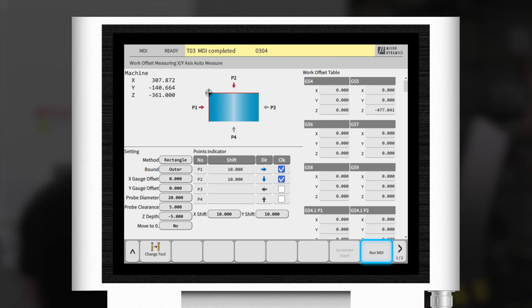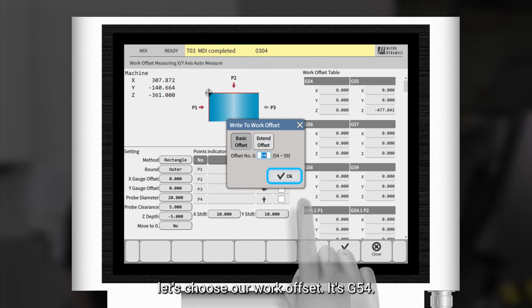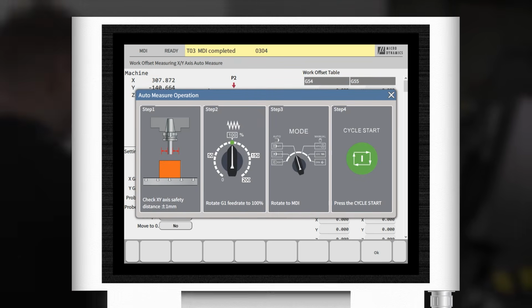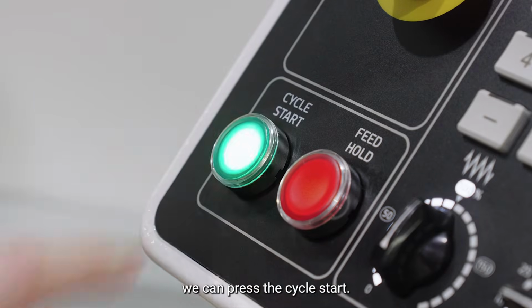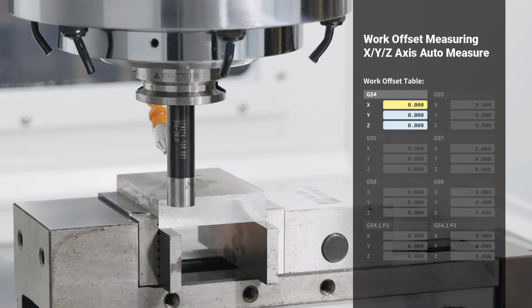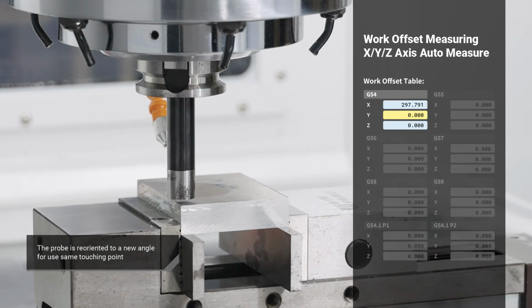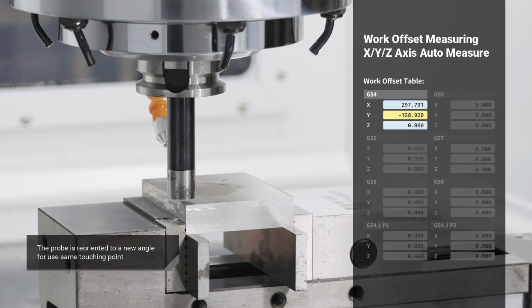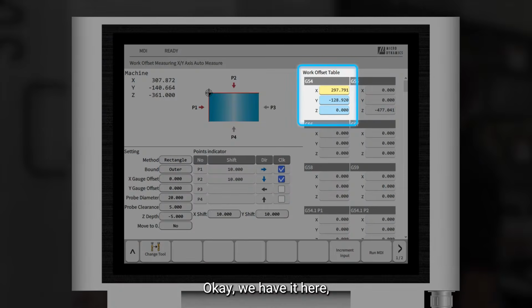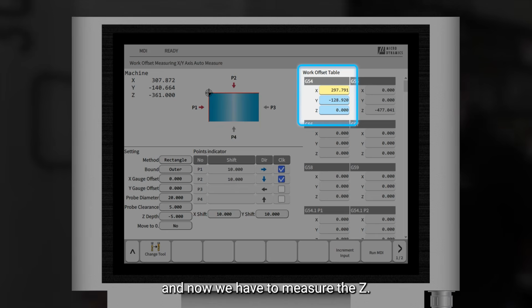The machine is going to do it automatically. Let's see. Run to MDI. Let's choose our work offset. It's 54. Let's check everything is okay. Let's put the machine into MDI mode. We can press the cycle start. Okay, we have it here. We have the X and Y G54 on the work offset table. And now we have to measure the Z.